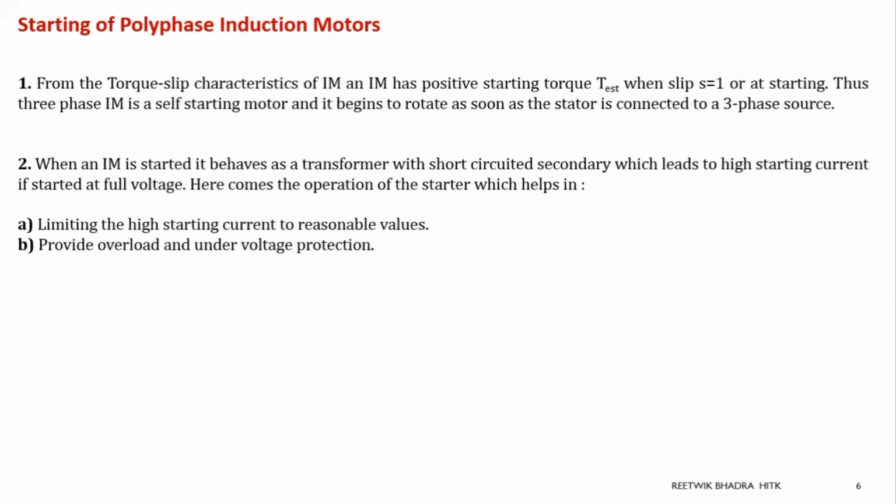Now going into our main topic. Our main topic for today is starting of induction motor. Now you know what is the function of a starter, because we have used a starter in a DC motor. It helped to reduce the starting current, right? So over here also a starter is used to reduce the starting current, and it is also used for over voltage and under voltage protections.